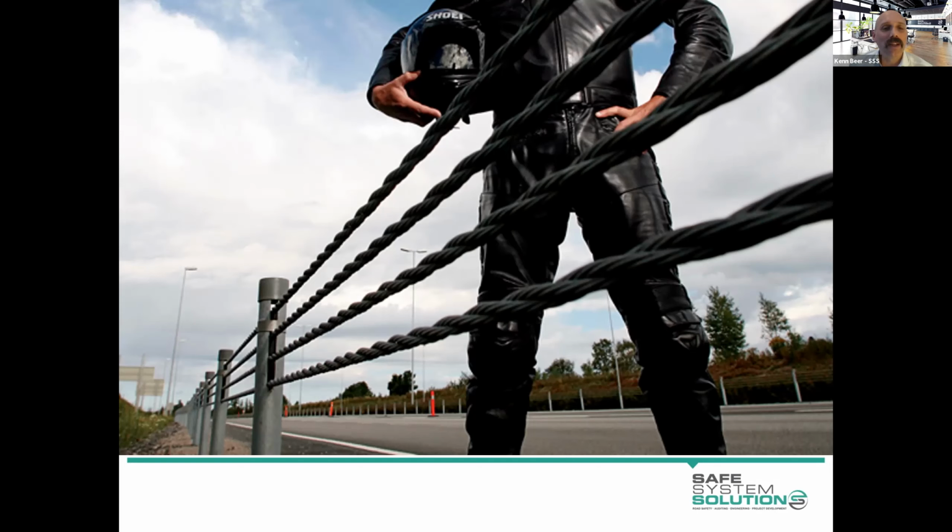But we don't use this product on those windy touring routes. It's on those straights. There's a lot less of it out there. But that being said, if you are designing a barrier system in an area that has high motorcyclist activity, this is not your barrier of choice. You'd use a flexible W-beam or a weak post system with its corresponding underrun protection would be the optimal outcome.